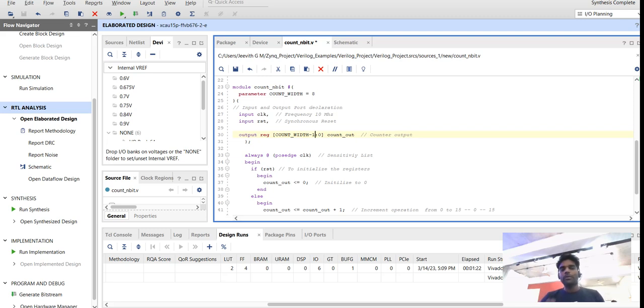Okay, so this will be useful when you have bigger designs. You'll put your counter somewhere as part of the design, and if you want to make a change, you cannot go and find that particular register. If you have 17 registers, in that case you would need to make a change there as well. So that's a problem. If you define the parameter at the top level itself, you just change the value here, and it will automatically get updated through the count width. So like that you can change the count width based on your requirement.